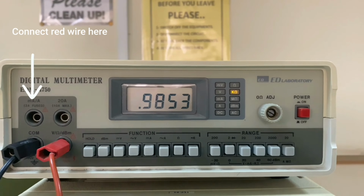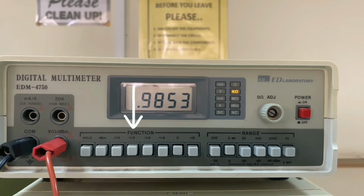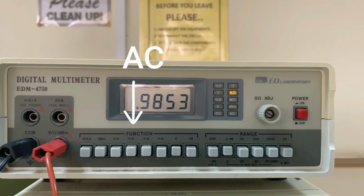After that, you need to choose the proper function you want. For example, if you want to measure the DC voltage or the AC voltage, this symbol means AC and this DC. In our case, we want to measure the resistance, so we choose this one. After that, you need to choose the range.